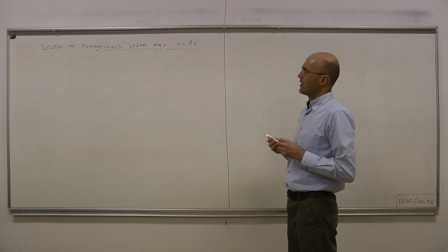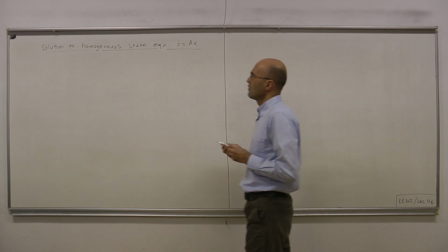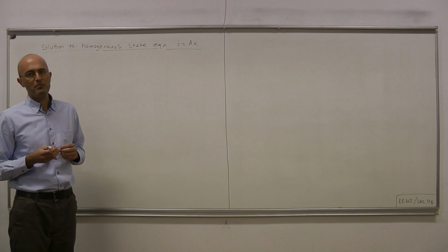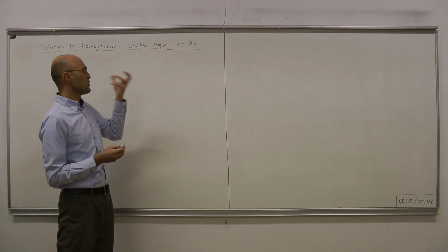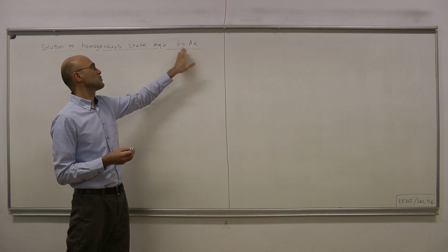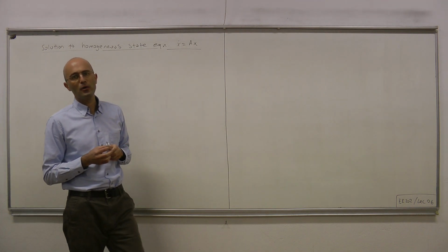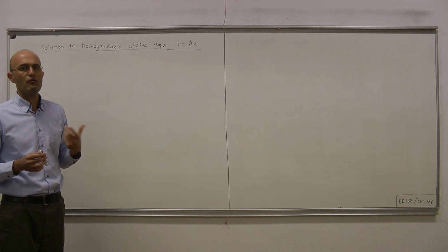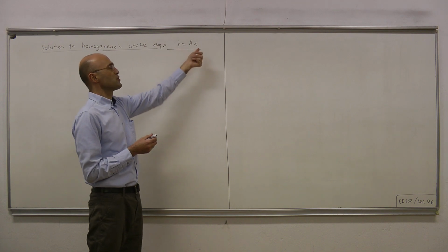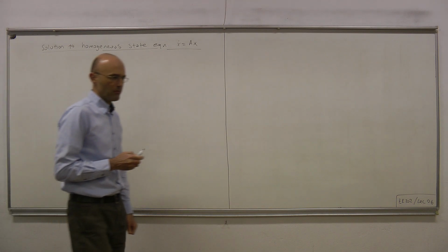In this lecture, we will discuss obtaining the solution for a given LTI state equation, x dot equals Ax plus Bw. And we start with this simple case where we don't have any inputs. So x dot equals Ax only. That means the solution will depend only on the initial condition of our dynamic components. And such a state equation without any input term is called the homogeneous state equation.